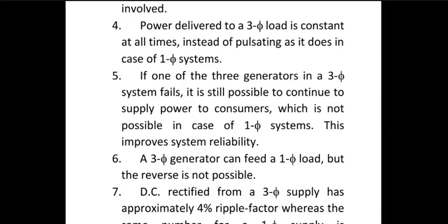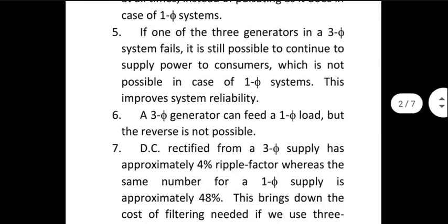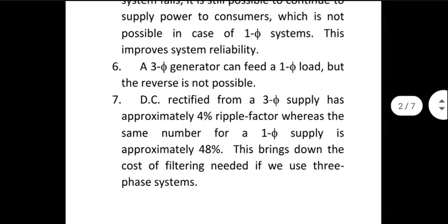Other thing is, in many cases, people want DC supply. It has been shown that if you are using three-phase rectifiers, bridge rectifiers in each phase, for instance, phase means each generator, the ripple factor is much lower compared to if you were doing the same thing in a single-phase system.